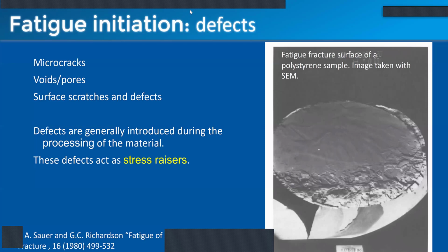Well, because the results may be inconsistent due to many factors like defects. Yeah, exactly. The cause of fatigue failure is those surface defects, and kind of by definition, defects are different from sample to sample or from device to device. And so we're going to get different fatigue life for each of those different devices. Excellent.